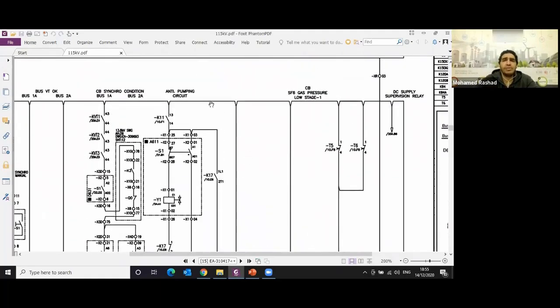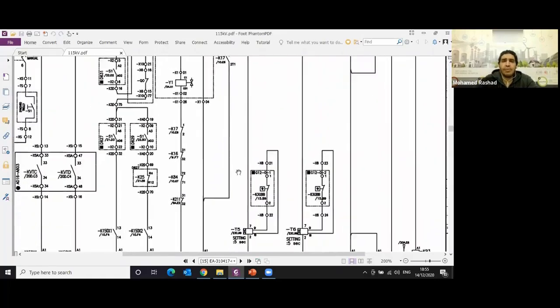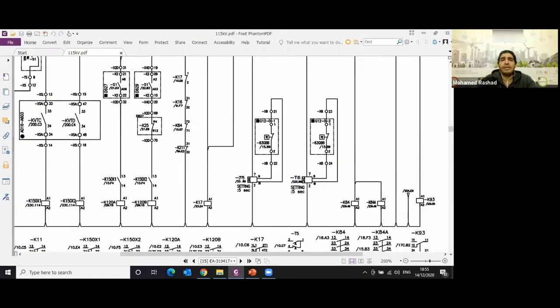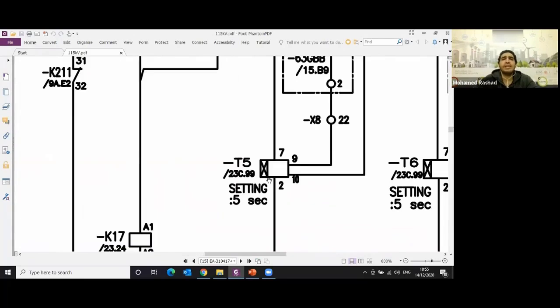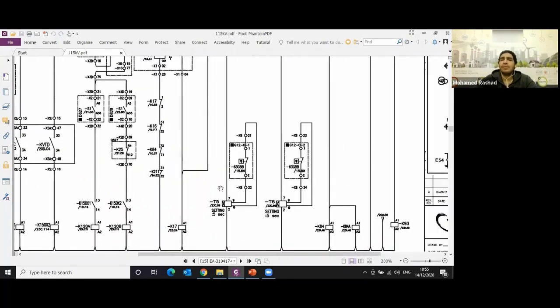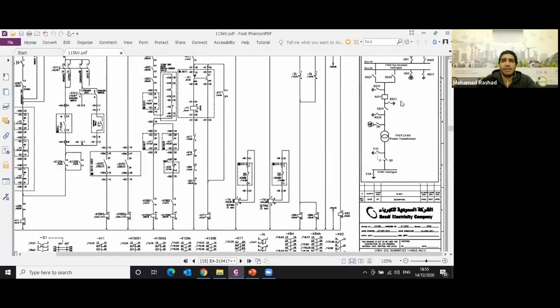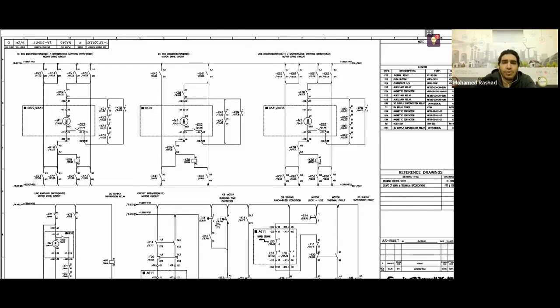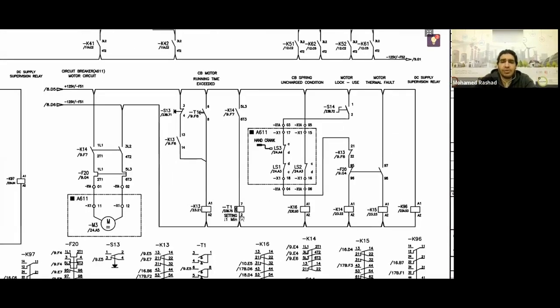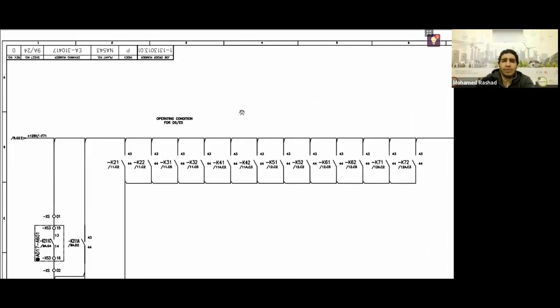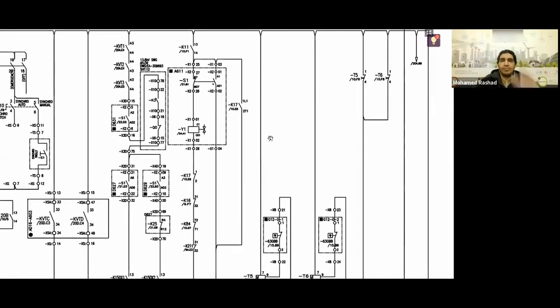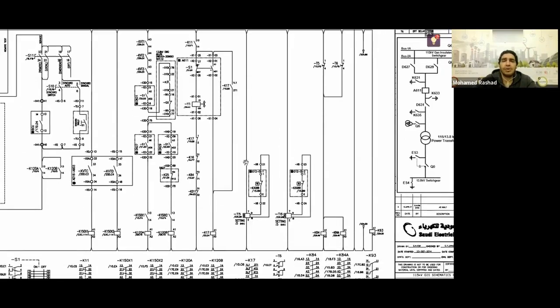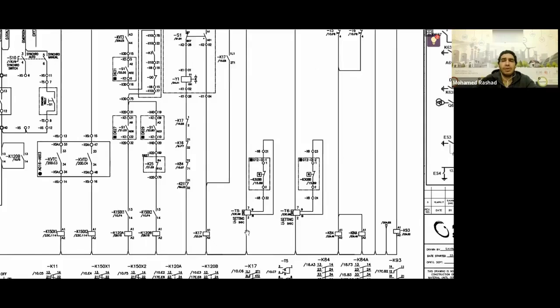So how does the situation proceed, gentlemen? Now you have the positive coming here from above and the negative coming here from below. Here is a timer, but this time, engineers, it is an off-delay timer. How did I know that this is an off-delay timer? As an engineer, the off-delay timer is always connected to both the positive and negative. Unlike the on-delay timer from yesterday, where the negative would have the positive cut off by a certain mechanism. However, the off-delay, and of course, if you refer to the bill of materials, you will understand that it is indeed an off-delay, is always connected to both the positive and negative.